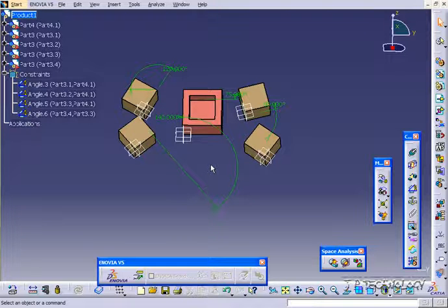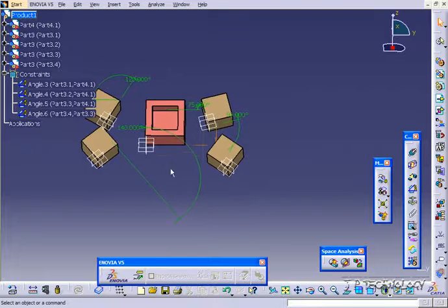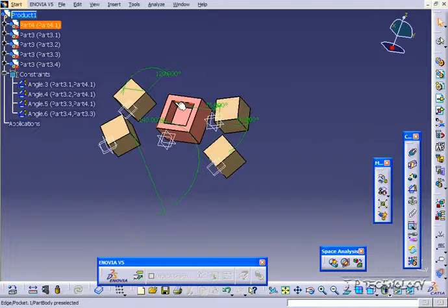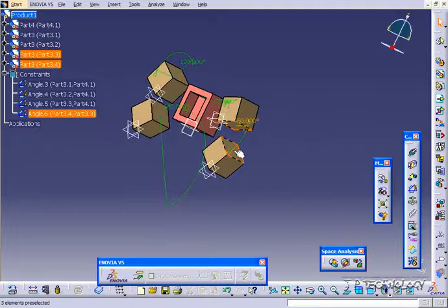So in this case, I showed you how to do this face, so one face to one face, a line to a line, and then this face to an inside face, and constraining this face to a face that's already been adjusted with the angle. So even after one that's already been constrained, you're able to use that face and make another angle constraint off of that too. So you're able to stack up a bunch of constraints from one another.